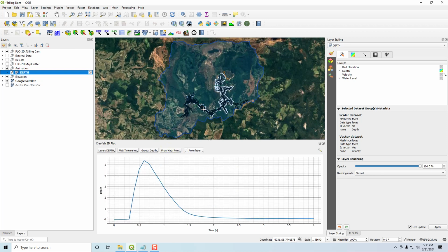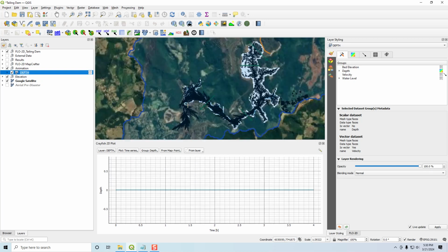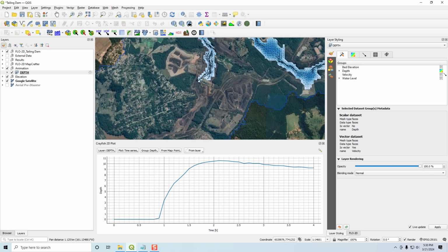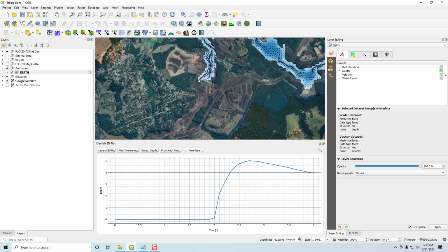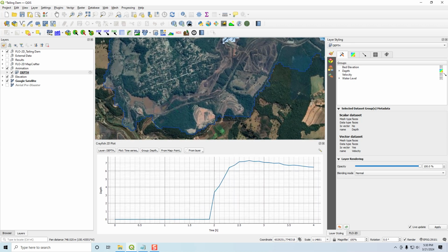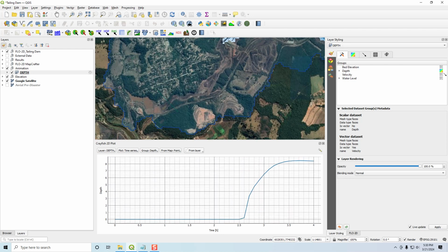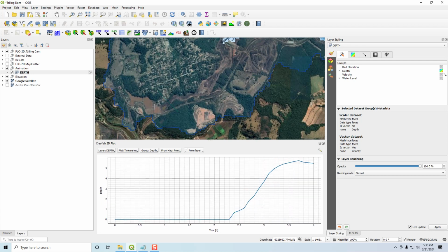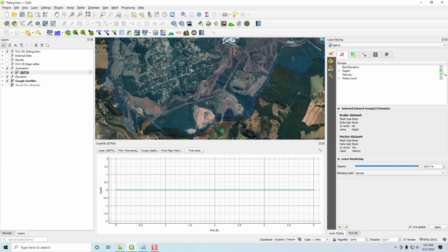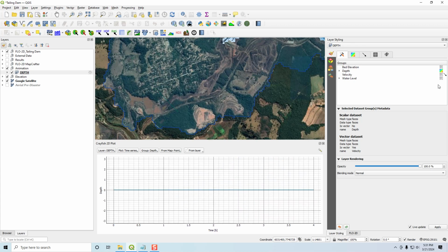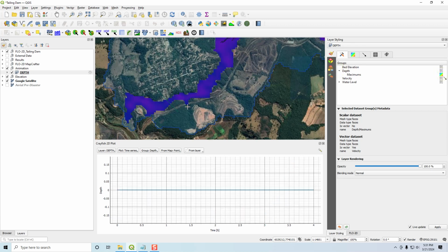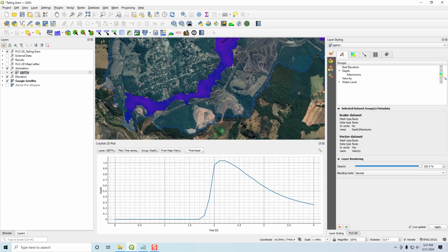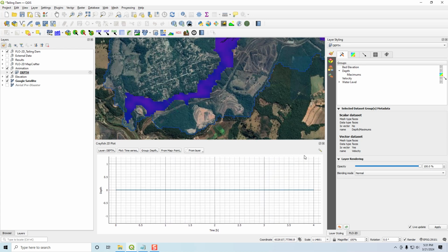Then as you put your cursor inside the area where there's flow, even if it's down here where the map hasn't reached yet, you get the plot of this water movement, sorry, this mud flow movement down to the edge of your map. And of course, if you go off it up here, you're no longer in the extent of the water. If you wanted to just put that on max, you'd be able to see that you could go up and get all of this data from this plot window. And that again is called the Crayfish 2D plot tool.